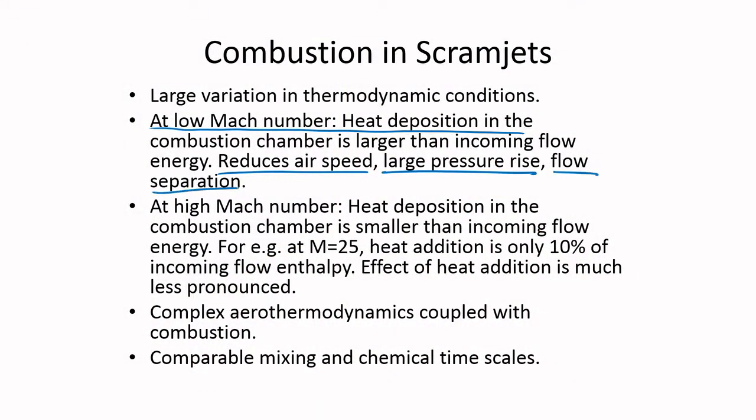So it does not mean that low Mach number operation of a scramjet is simple. A Mach 2 operation is not simple, whereas at higher Mach numbers the heat deposition in the combustion chamber is smaller than the incoming flow energy. For example, at Mach 25, if at all it is possible, there is no such Mach 25 scramjet engine, the heat addition is only 10% of the incoming flow enthalpy. So this is not really useful.